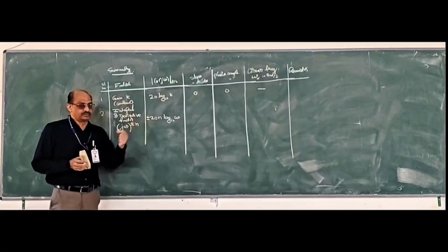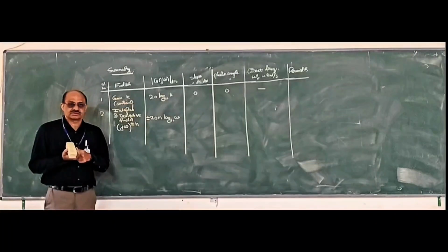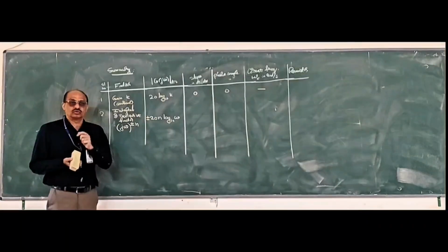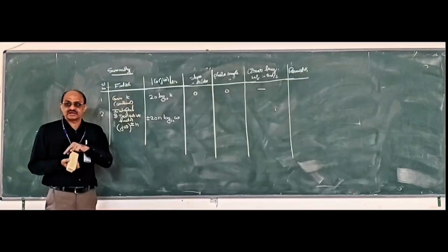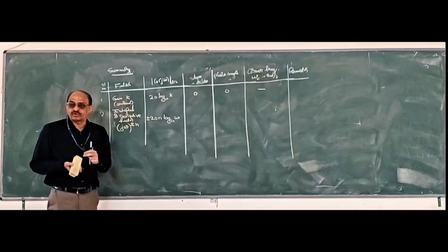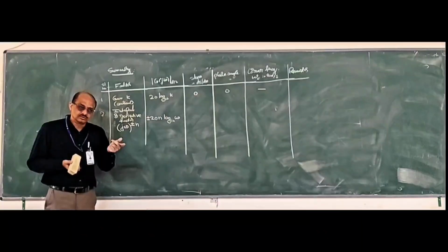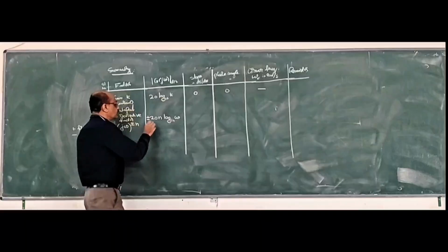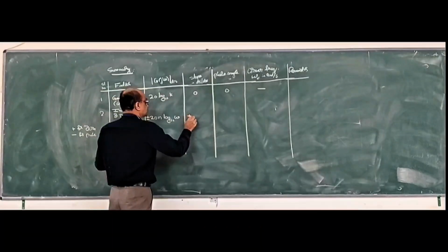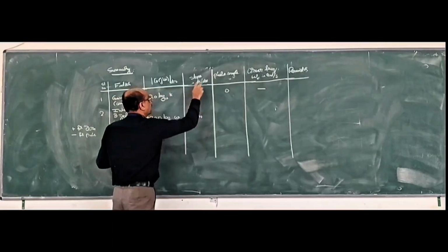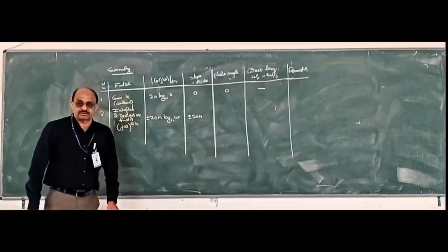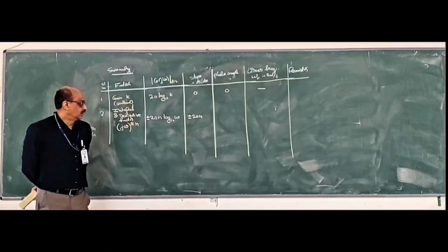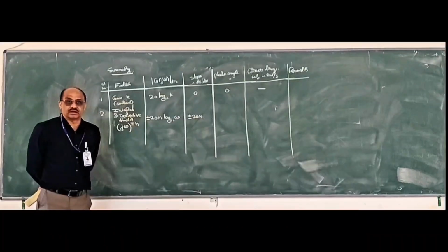If n equal to 2 poles are there, then minus 40; for a zero, plus 40. And then slope is plus or minus 20 n dB per decade.